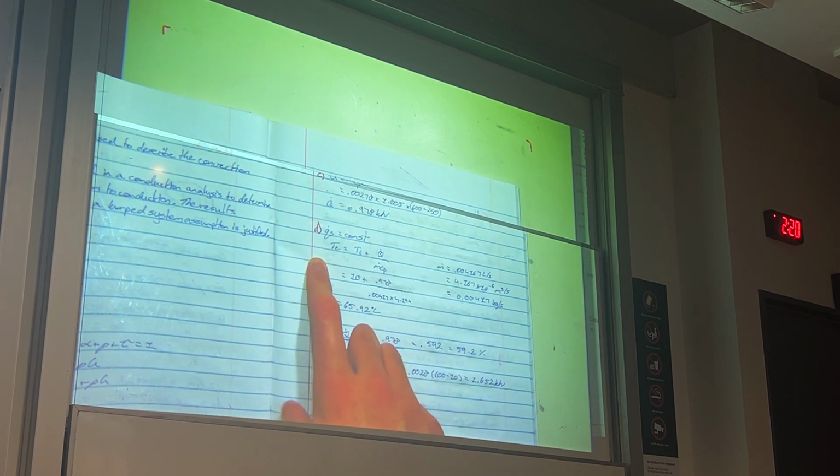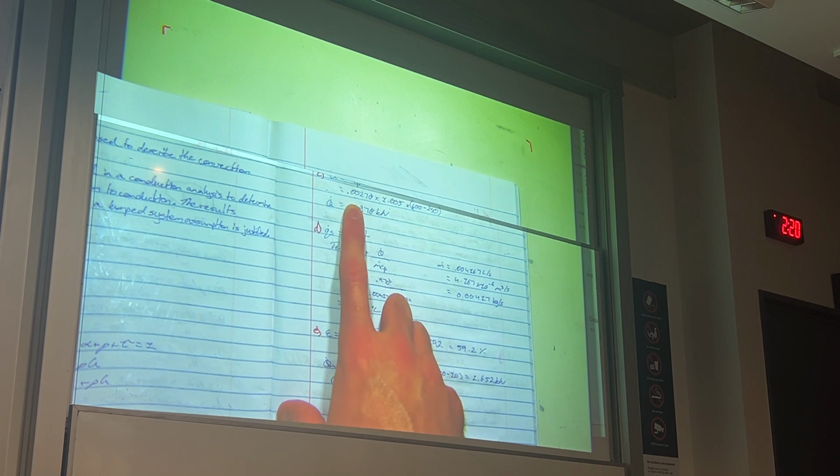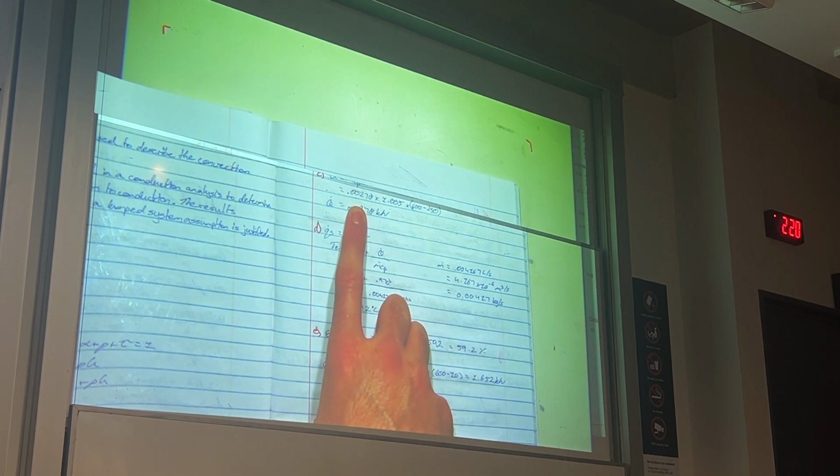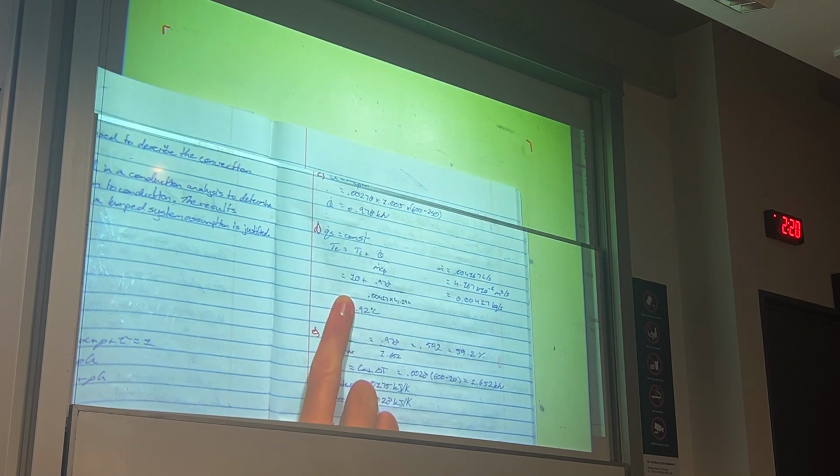So assuming an ideal gas, we can use m c_p delta T. So we can determine our mass flow rate in kilograms per second. So we're going to have to convert 10 kilograms per hour into kilograms per second. And we determined that the maximum heat that we can transfer is 0.978 kilowatts.